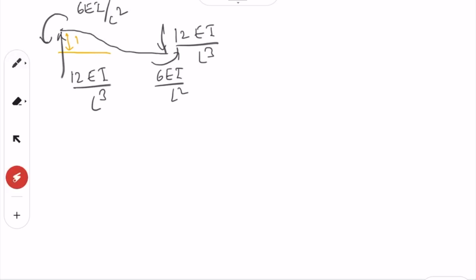So you have this system like this one, and you know these are the real forces basically, meaning that if you apply a displacement in degree of freedom 1 only, then the force that you have to apply here will be this, and along with that you have to also apply a moment of this, and since this end is fixed, because of this there will be these end moments and end forces which will be induced.